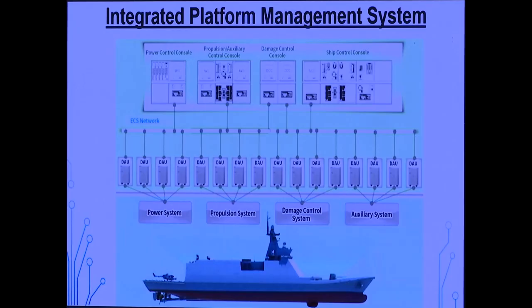A similar version of this is the so-called integrated platform management system or the integrated machinery control system, which caters for the float and the move components of the warship. As mentioned earlier, these are various engineering equipment and systems that are part of the warship. This representative picture shows the power, propulsion, damage control, and auxiliary systems feeding their sensor data to data acquisition, which processes the data and sends it to the data bus continuously. Various consoles across the ship can access this data to monitor, further process or control these systems from these consoles in accordance with the authorization and the security layers provided in the system.